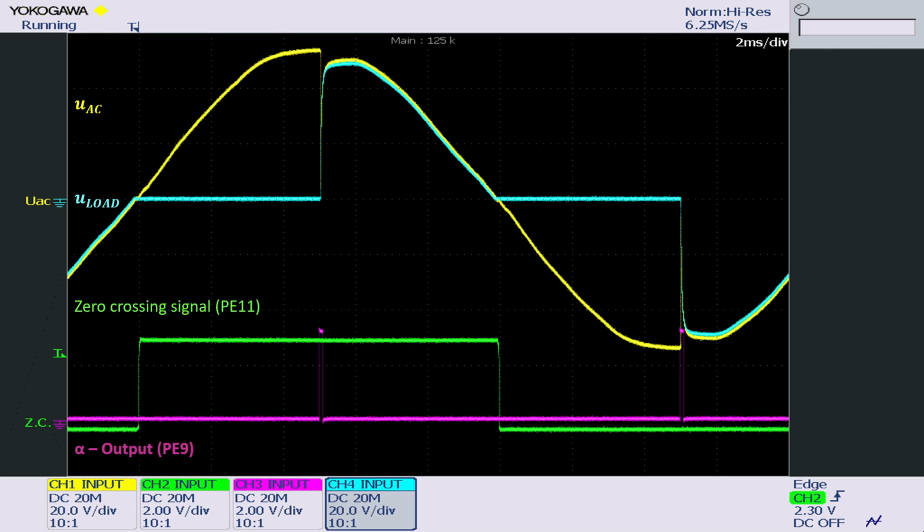After powering up the circuit and flashing the firmware into the microcontroller, we can see the following waveforms on the oscilloscope. As you can see, the TRIAC control signal looks fine since it triggers the TRIAC right in the center of each half wave, like it should do using the earlier discussed C code. Also, the clamping protection of this signal obviously works fine as well.